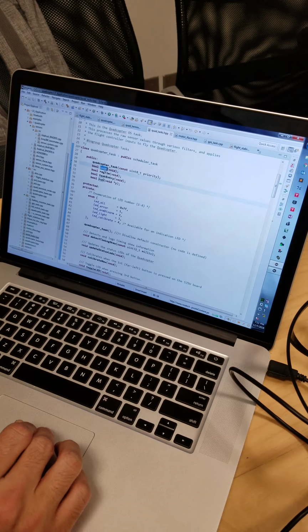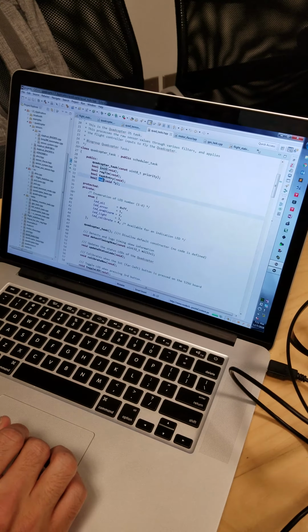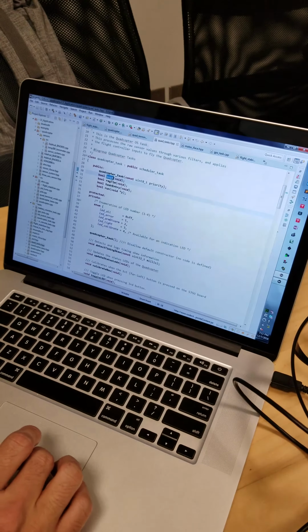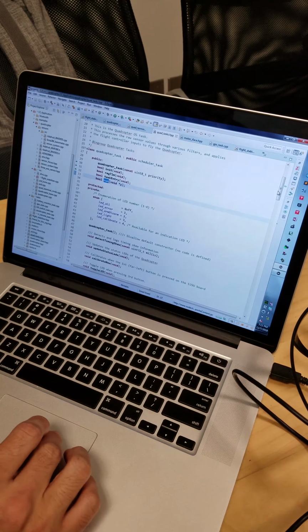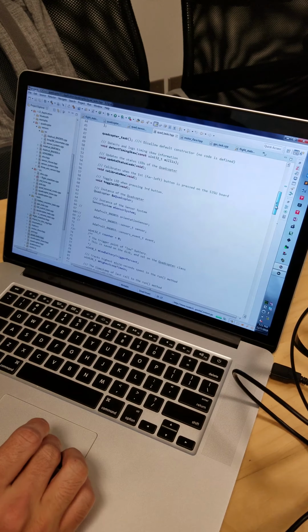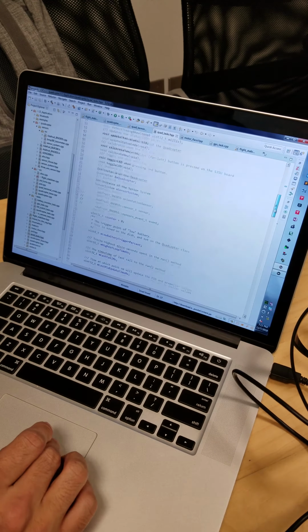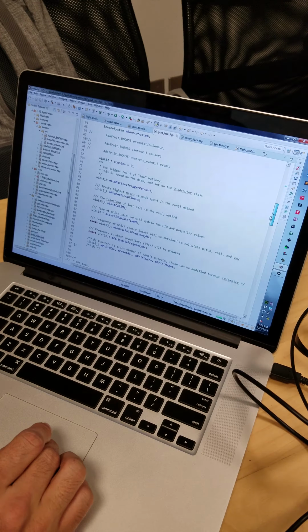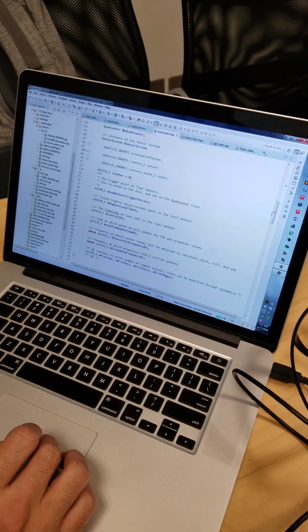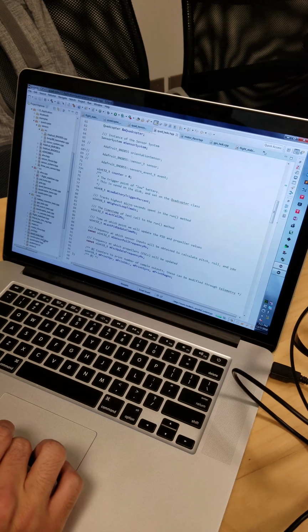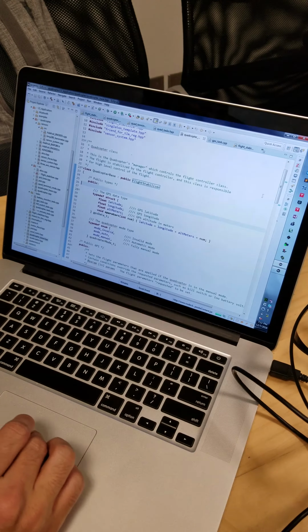And so basically we have our init function, which is processed during init before the RTOS starts, and our run function. Our run function does many things. It processes sensor data, updates LEDs, performs calibration, and basically is the control loop or the thread of the operating system. And here we have our quadcopter base.